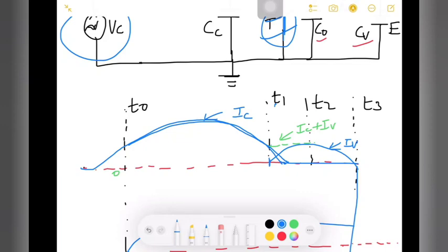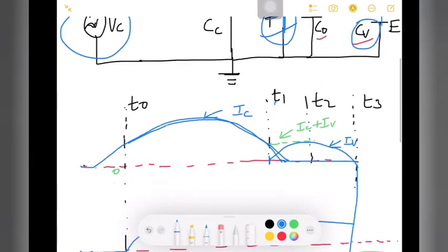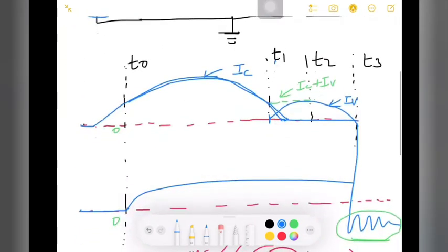And your triggering gap G, the 3 electrode gap G, will be closed, and the high frequency current from the discharging capacitor CV also flows through the arc. So current will flow through the arc from the discharging capacitor CV. At a time T2, when the generator current becomes 0, you can see here the blue line is 0.